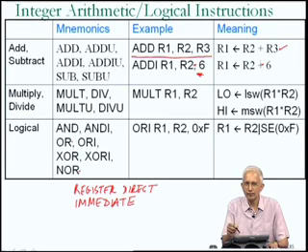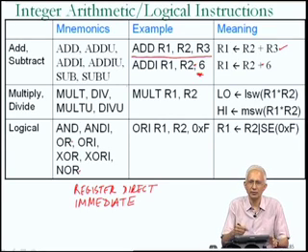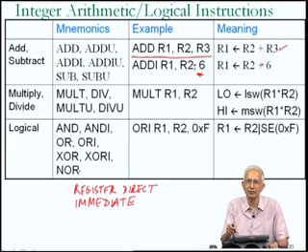And that would sort of motivate the reason for not having a subtract immediate instruction. There is no need to have a subtract immediate instruction, since if there had been one, it would have just had a positive value of 6 as the second operand, and I can achieve the same effect by having a -6 as the second operand for the add immediate instruction. So the designers will avoid having instructions which are not necessary, in the sense that if the functionality of subtract immediate can be met by the add immediate, then there's no need to include the subtract immediate instruction. It would just be a waste of the hardware, because the hardware would have to be a little bit more complicated because there's one more instruction.